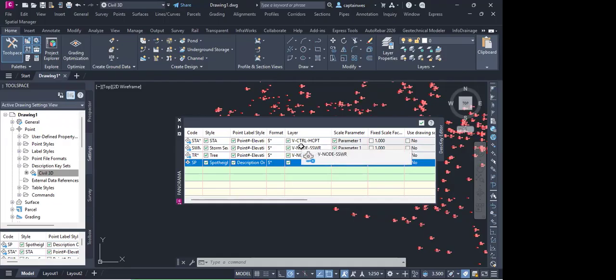So in that regard, I normally advise when you introduce a new element or a new feature in the drawing, just create a new layer for it. For example, we've introduced the spot height. It is us who know what a spot height is. The software doesn't know. So we don't go ahead and pick a layer that the software knows where it's going to use it for. We create our own layer.